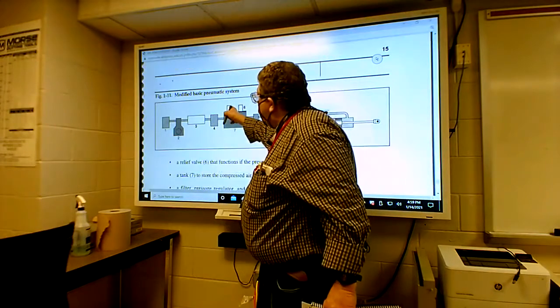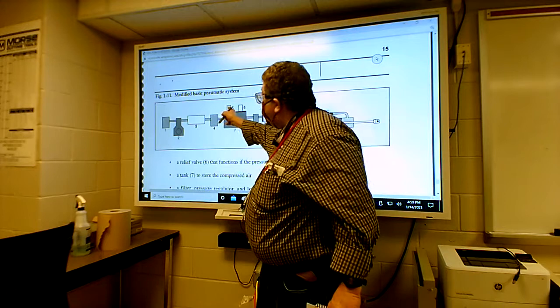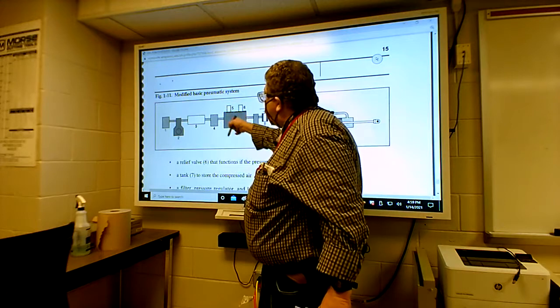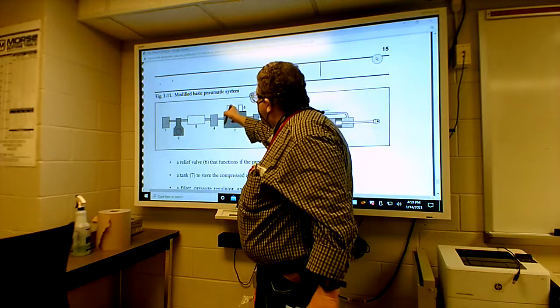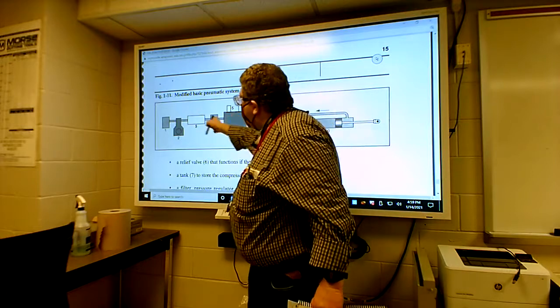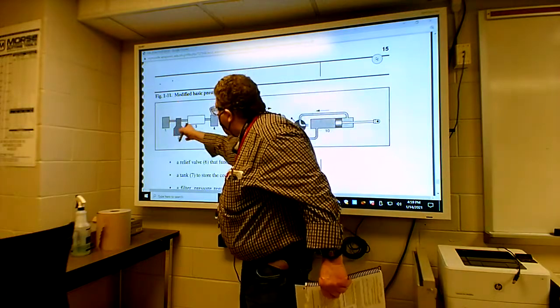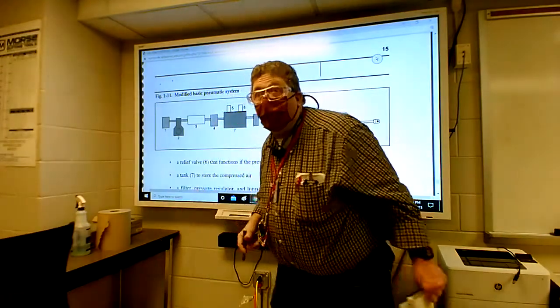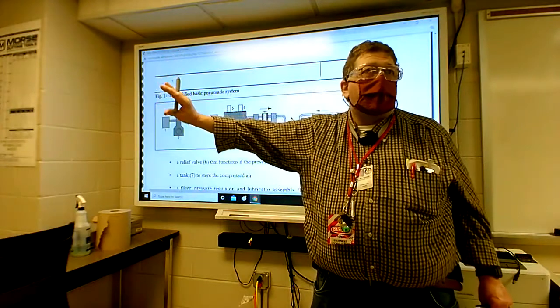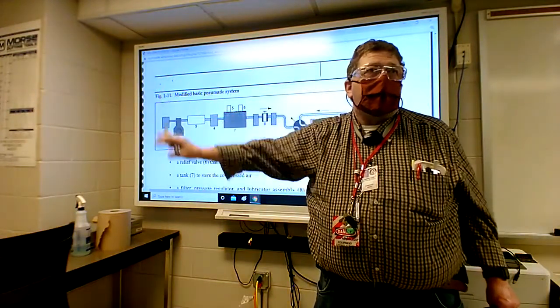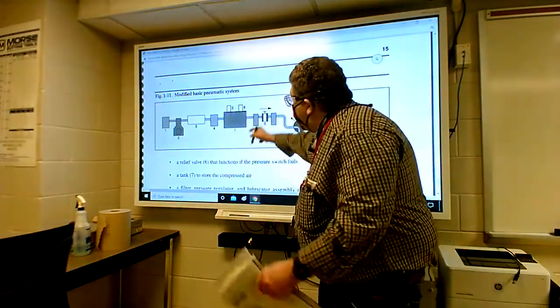And so this is the downstream watchdog basically that says, if this gets over the set point of that sensor that's been set, then it's going to shut this off. It's going to say cut off because the vessel can't take any more, or the process never wants any more than 90 pounds, so you have to shut off. And then after that, I know it's time to go.